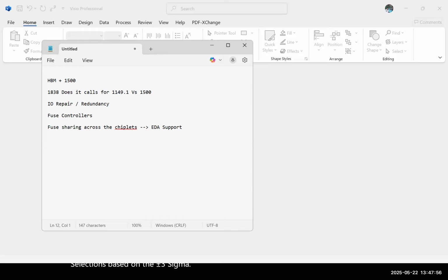So Bala, in summary, if we have to provision for a multi-die fuse blowout, we have to assume that it may happen at the wafer sort, or it will only be possible at the package level. In a 3D hybrid bond example, where there is no wafer sort, the fuse blow will probably happen at the package level. That's the worst case I'm talking about. Let's assume the problem statement is that you have to blow the fuse of one die through another die, in a stack configuration.